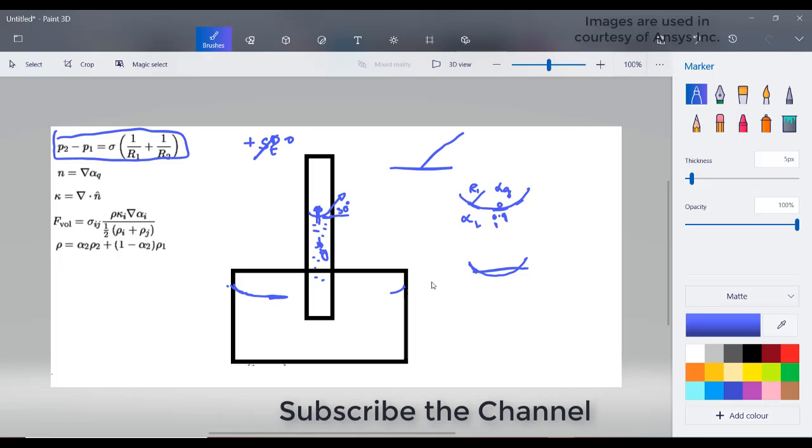That N and kappa, which involves the del operator, give the source term F wall that you can see here. Sigma ij is the surface tension coefficient. Kappa i gives the directions, and grad alpha i is the gradient of the volume fraction.